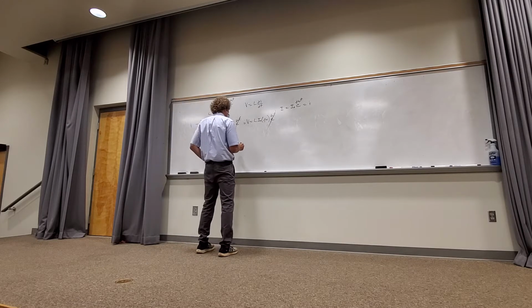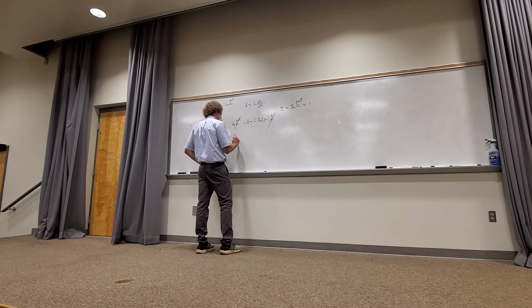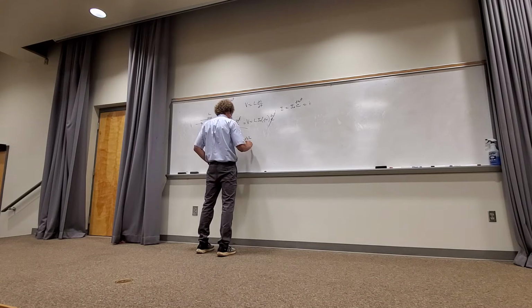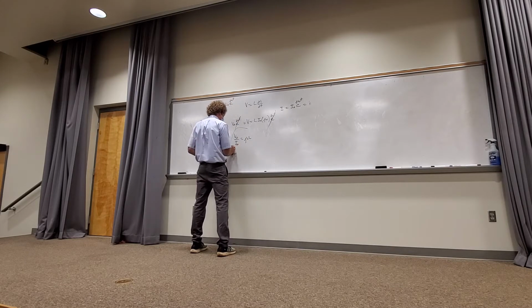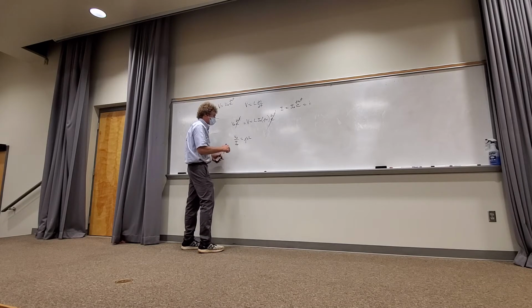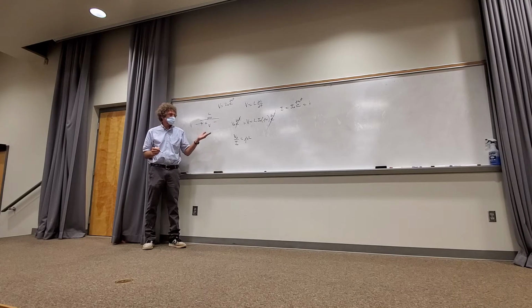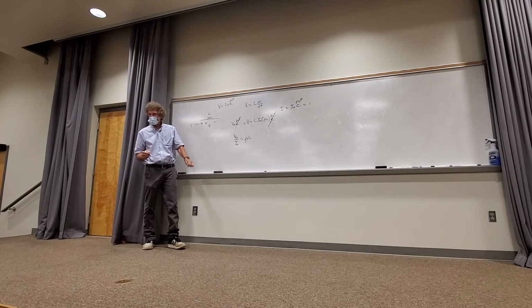And when I take a look at the ratio of V naught to I naught, it's really going to be j omega L, right? And this right here is going to be very important. Everything else cancels, and I get the ratio of voltage to current is j omega L. You with me? Remember, j is a complex number. Technically, it's the square root of -1, but really, it's a construct to help us solve problems. Think of it as an intermediate step.